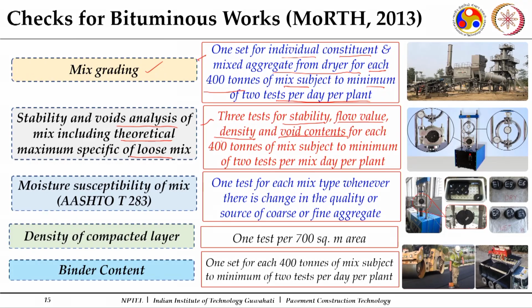Simultaneously you can have samples from your bituminous mat which had been constructed and compacted also. You can core that particular mix, bring it to lab and ensure density, stability and flow values. So there it says subject to a minimum of 2 tests per mix per day per plant.